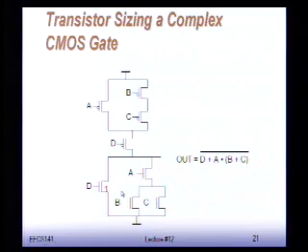Because there are two worst case delays, we not only want them to be equal to that of a reference inverter, but we also want them to be equal between themselves. So you can discharge either by pulling up D here, or by pulling up A and one of B or C. And we want the speed of these two to be the same in the worst case of each branch. So the branch that has D only.